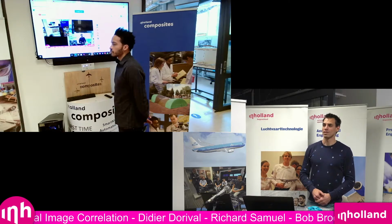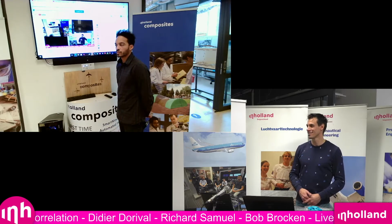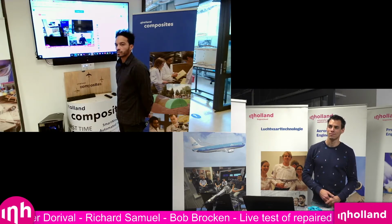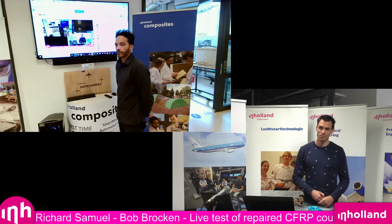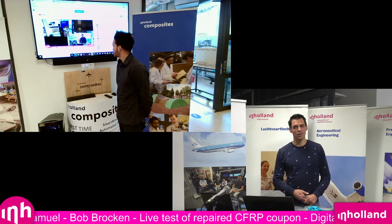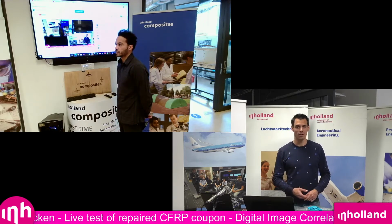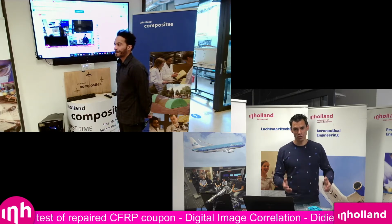How far is the processing? It's about 80% there. It is one of the disadvantages of DIC that the test can take a little longer than what a common extensometer can give. We originally thought we needed a camera with as many megapixels as possible, because then you get more pixels over the same area.